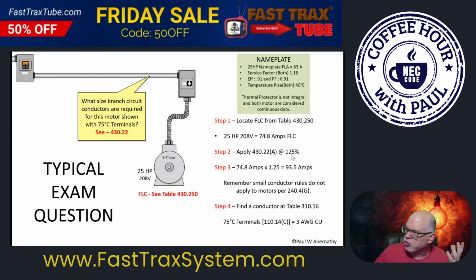Ignore the A there, because it's not A, it's just 430.22. So 74.8 amps times 125% is 93.5. Remember, small conductor rules don't apply to motors. We get that advice from 240.4(G). It's referenced by 240.4(D), which is the small conductor rules. And then we go to 310.16 and we find a conductor under the 75-degree rating, and it was a 3. That's all you do if that's what the question is.